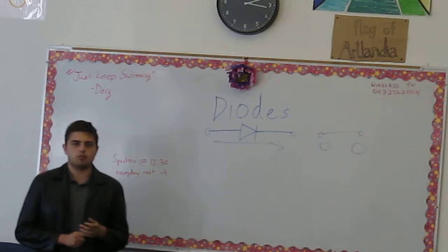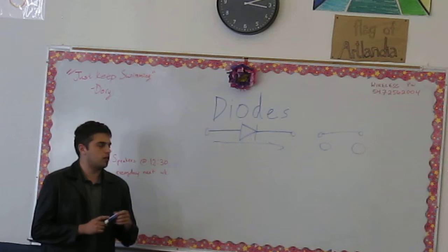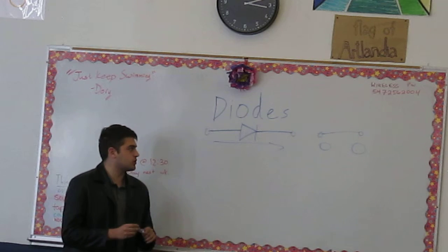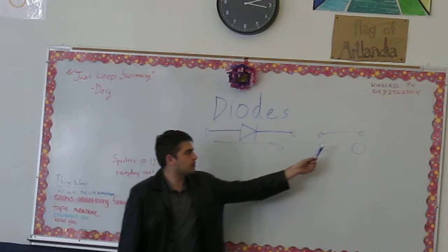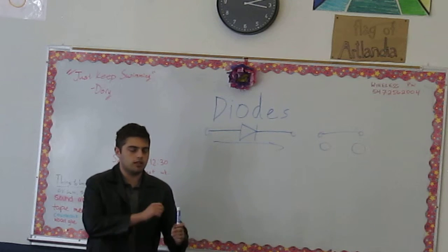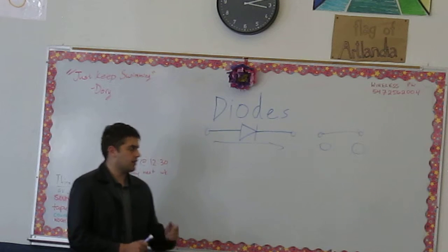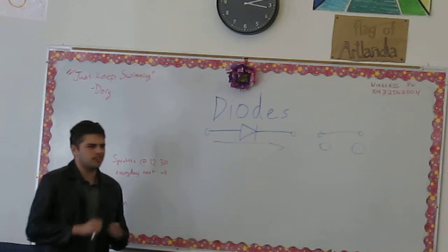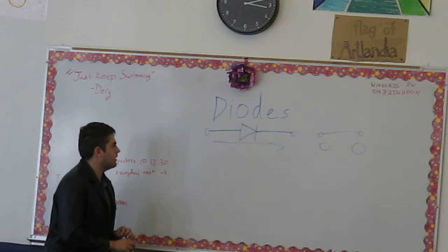This is what even professional engineers do when they look at a circuit and try to figure out what's going on. They don't go through all the mathematical equations, the math and the graphs, immediately in their head. So you look at a circuit that has diodes everywhere, and you think, let me imagine current going one way. Let me replace all these diodes with shorts. And let me think of it the other way: let's replace them all with opens. That's not a good way to think of it, but it's a quick way, so you can get an idea of what's going on in your circuit.